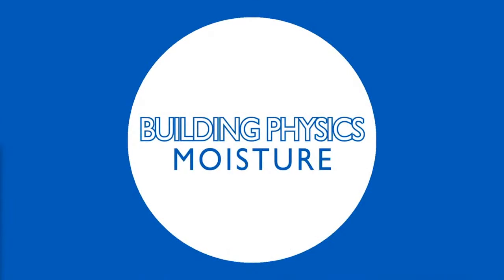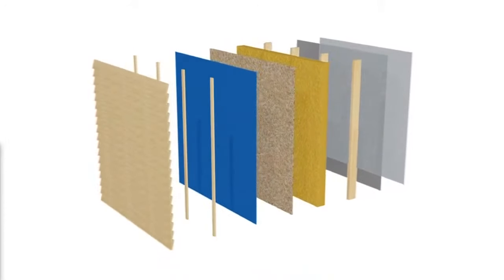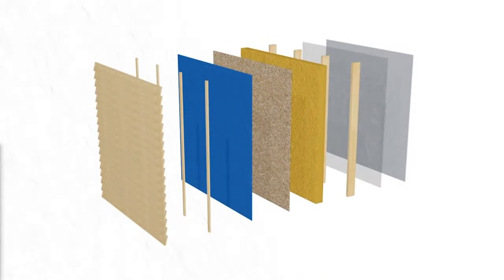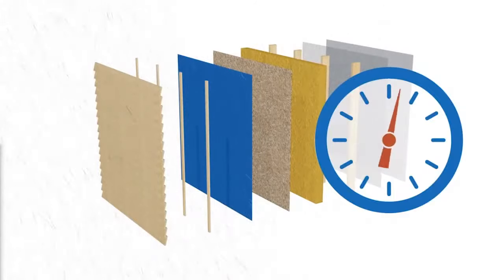Controlling and managing the moisture flow in a building is fundamental to maintaining the durability of the building envelope, maximising energy efficiency and protecting the health and safety of the occupants. There are a number of potential moisture sources affecting all building envelopes, the most obvious being the external environment, weather and rain. While buildings are designed to be weather resistant when they're completed, they can still pick up a lot of moisture during construction. The longer the internal fabric of the building is exposed during the build process, the more wet materials like concrete and mortar are used, the higher this moisture load will become.